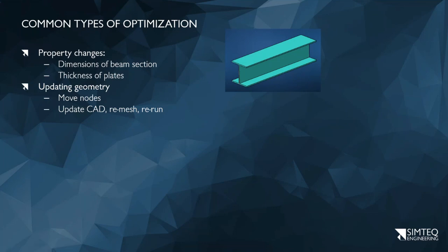That is surprisingly painful to do, but entirely possible. It's definitely not impossible. Well, for updating CAD, if I make the radius smaller, I also need to mesh finer in that radius, otherwise my error becomes larger. So you have to be really careful if you do this to ensure that you've got a fine enough mesh, or are measuring the important locations away from stress concentrations.